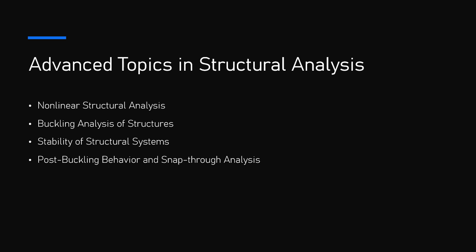3. Material properties. The modulus of elasticity, E, and the yield strength of the material significantly influence buckling behavior. Materials with higher stiffness, higher E, can withstand higher buckling loads. Material plasticity plays a role in inelastic buckling, where the material can undergo significant plastic deformation before the structure reaches its ultimate buckling capacity.